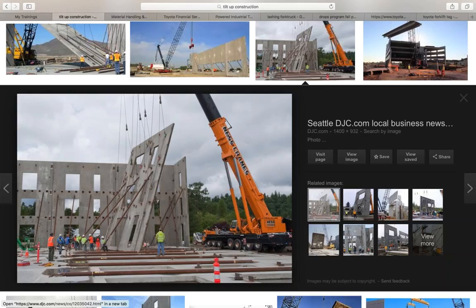Also, we're going to reinforce steel with vertical structures like piers and columns, making sure that they're guyed down or tied down, right. We're going to report any unsafe conditions. Like we talked about, we're going to use plastic caps on exposed ends, especially the vertical ones. Anytime there's an impalement hazard is when we have to use a reinforced cap, okay? Also, we're going to use pliers to bend down loose ends of any wires that we tie. And what I'm talking about now are the wires that tie rebar together and that we'll be using to bind rebar together.